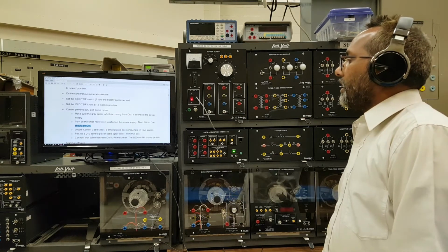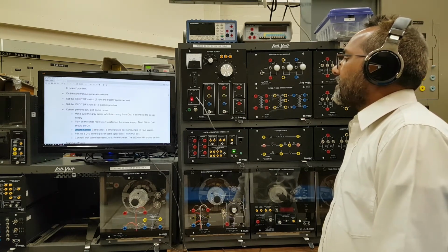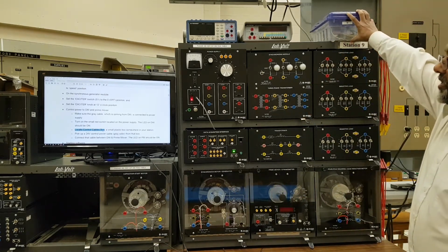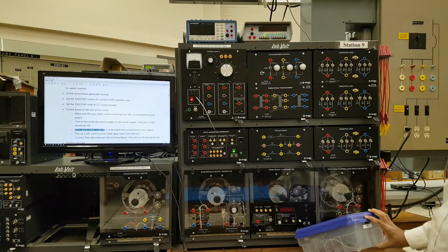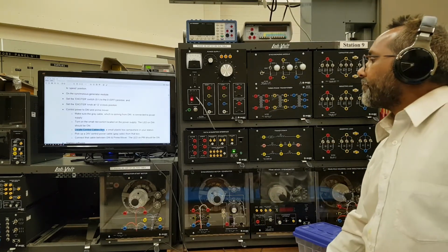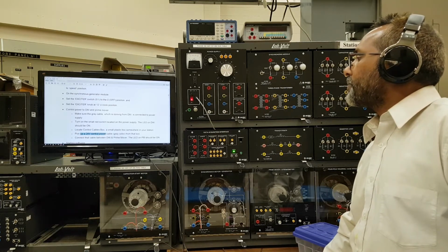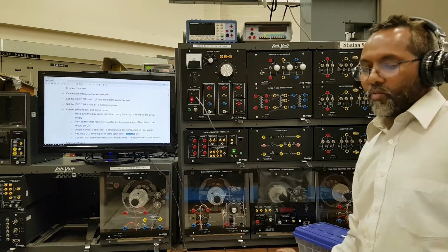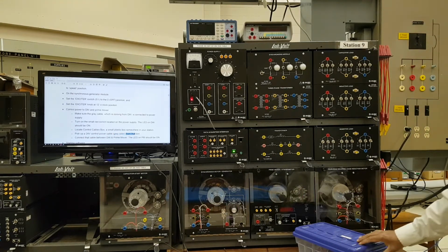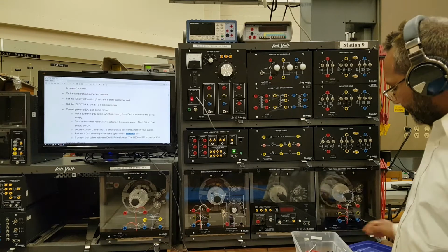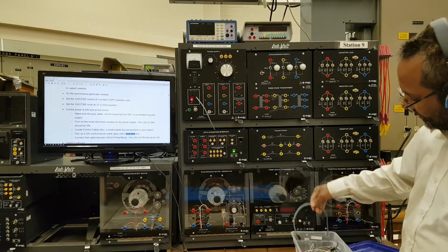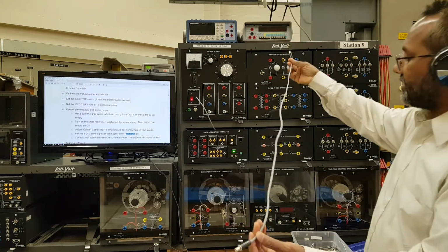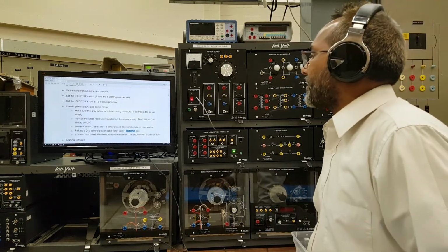and it would communicate with the computer. So locate the control cable box. There is a control cable box here, a small box somewhere in your station. That is the one we located, and then pick up the 24 volts power supply gray color cable from that box. Let me see, if I open it, I can see some cables here. This is the gray color cable it's talking about.